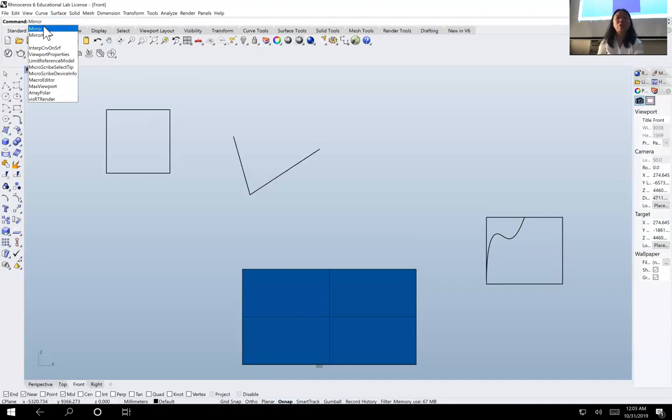So now what I'm going to do is mirror the line I just drew, make a copy of it, a mirror image, so that it looks like the window that I envisioned. So I type in mirror, then select object for mirror. I select this object and press enter when done. You always read the command prompt; if you don't, you would be lost very quickly because you would not remember, unless you do it many times. A copy, yes, which means I will have two of them.